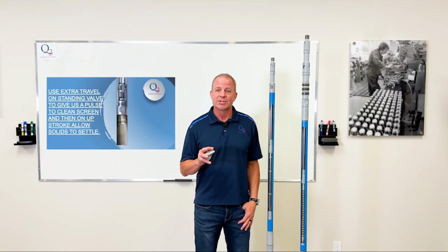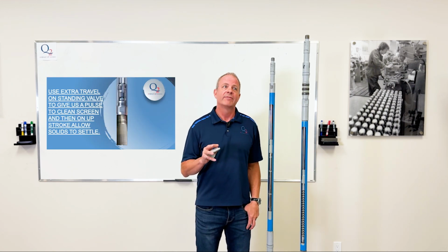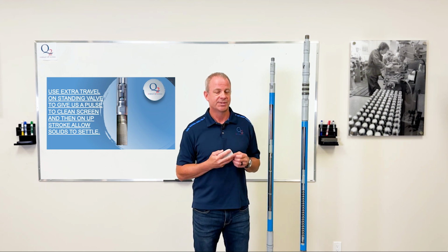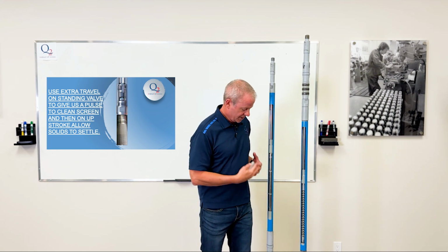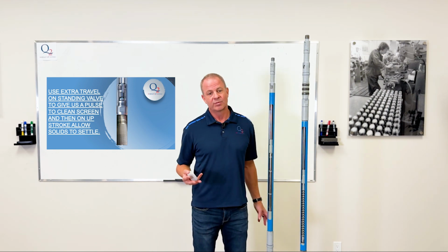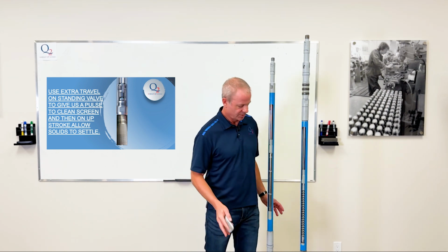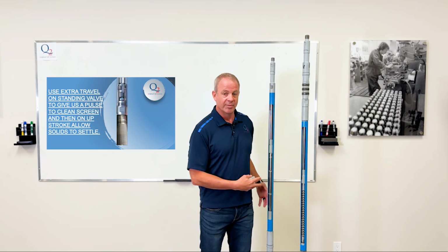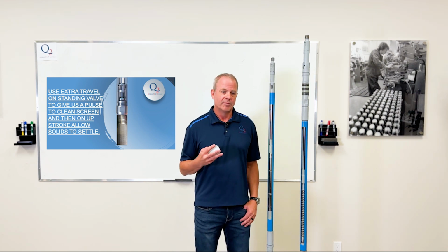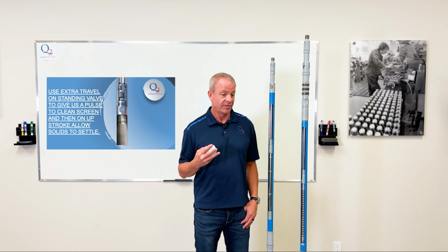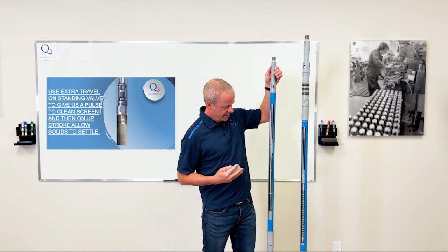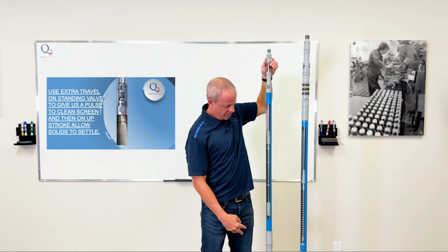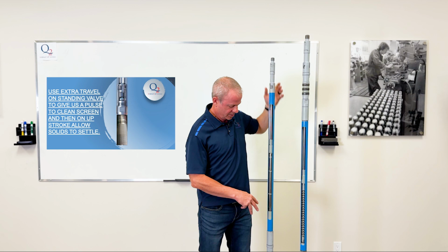This slide here is interesting because we took some information from the drilling guys and said, well, your first line of defense is screens. Well, in the production world, in this type of geometry, it's very difficult to run a screen, right? Because as soon as they plug up, you've got a small cross-section area, the screens plug up and then you starve your pump. So we thought, why don't we develop a device that's self-cleaning? When you stroke your pump up and down like this, you always have a part down below where you have no movement and the solids can settle out.